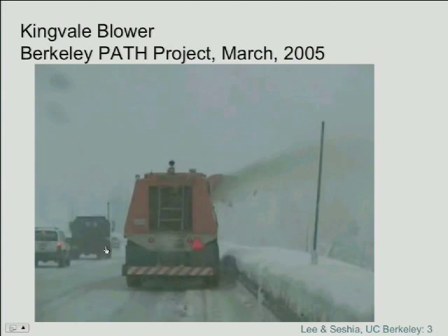Now, why does that work? Well, you can think of these sensors as samples of the road location. And as with any sampling scheme, there's the risk of aliasing. Aliasing means that the snowblower could decide to follow a path like that, but that would be stupid. So you design the snowblower so that it chooses a lower frequency of bends rather than a higher frequency of bends, and then you don't have to put the magnets quite so close together. You use your knowledge about the structure of roads to determine how far apart you need to put the sensors.